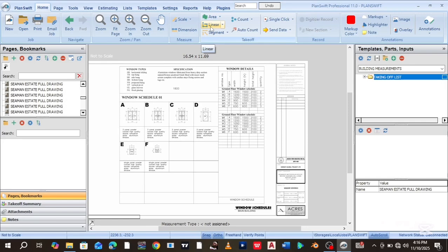So after we measure with the linear item, we need to feed it a second parameter. Let's say we measured block work with the linear item, and we know that block work is not measured in linear meters, it is measured in square meters. So all we need to do is measure the perimeter of the block with this linear tool, and then feed the software, in the formula, a new parameter, which is the height.